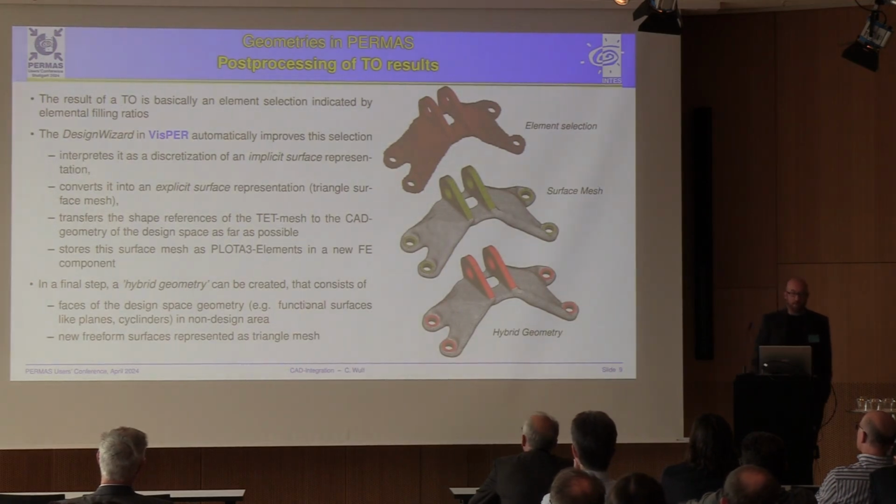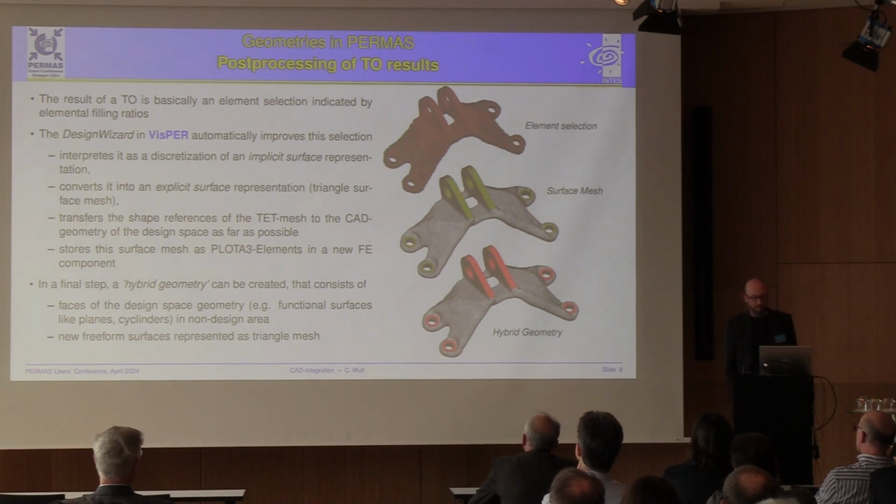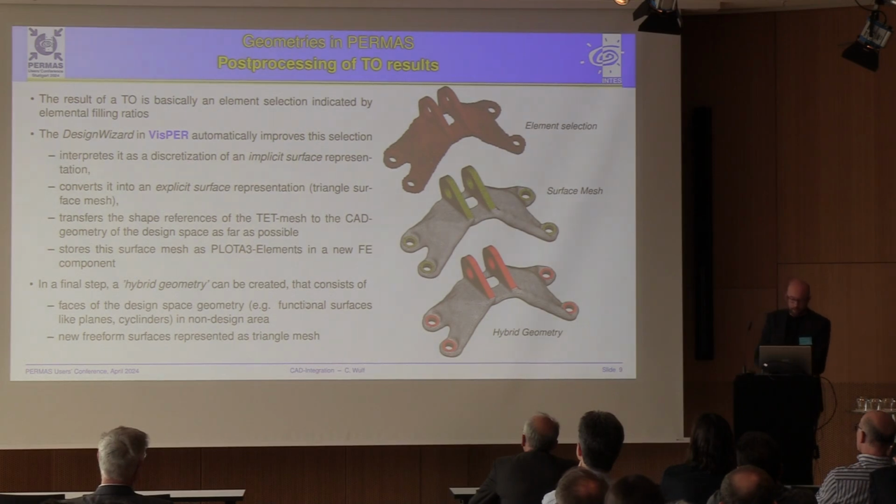Now, with these two basic ingredients, we extended our so-called design wizard in VisPER that generates geometry representations of the results of a topology optimization. First, the result of a topology optimization is basically nothing else than an element selection that is indicated by elemental filling ratios.